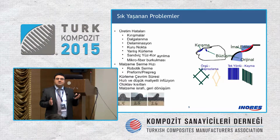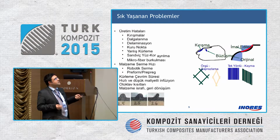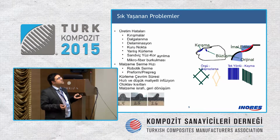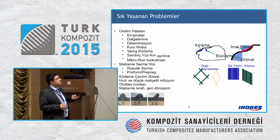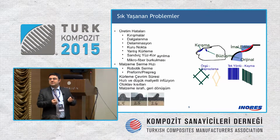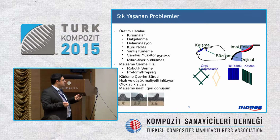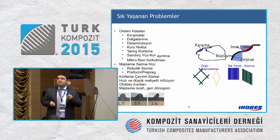BMW for E series, they have the production time of 7-8 seconds for a plate. It is a cure system, therefore you can achieve a certain geometry you desire. Sometimes you can't because the material might shrink, and the single-sided fibers can change angle when they are being carried. These are the challenges of composite production.